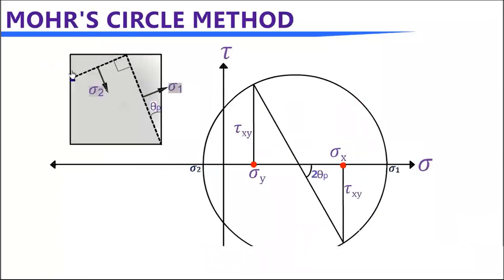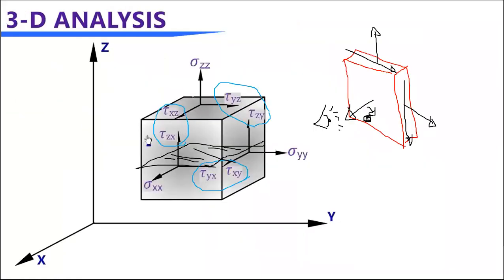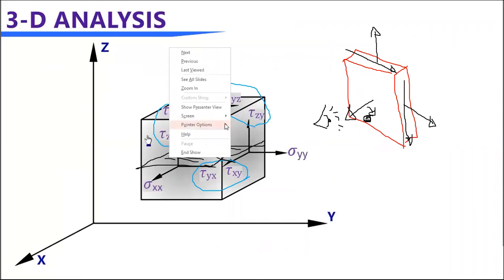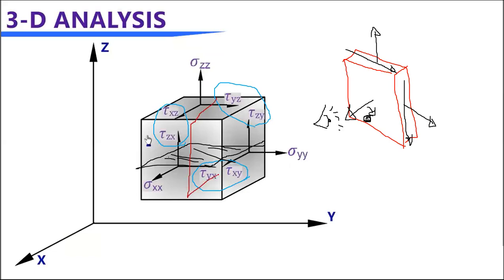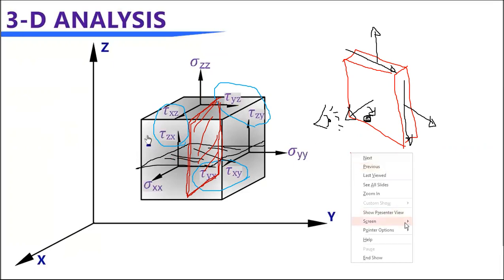Now this is in 3D, right? And think about the X and Z axis. So you will have an element like this, and that will be rotated or stretched out, something like that. So we can still use the same principle in Mohr circle and solve it in 2D and assemble that. And for instance, the other axis, what's that? That's the ZY axis, right?